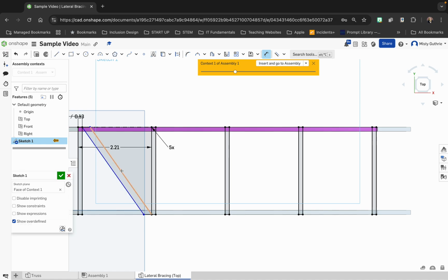Again, if you're dimensioning a diagonal, do not come down here and dimension it at 1/8. If you do, it's going to be too skinny. And you can probably eyeball that and tell that this is skinnier than that one. If I try to do this across at 1/8, I get all these errors. And that is because you cannot be 1/8 here and 1/8 there. So you've got to get rid of that other one if you accidentally do that.